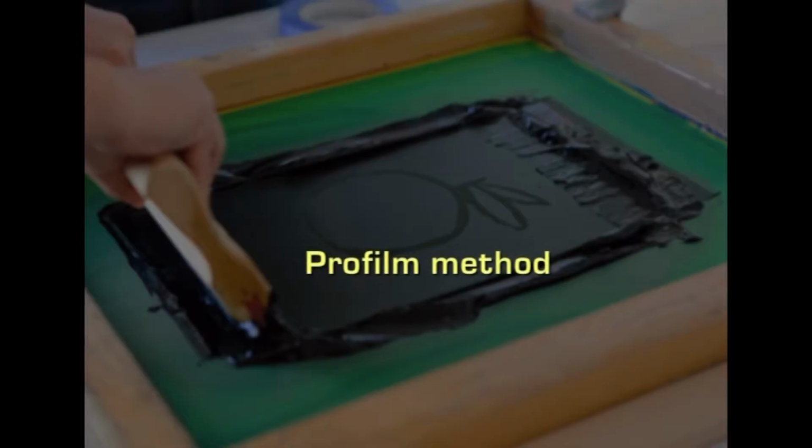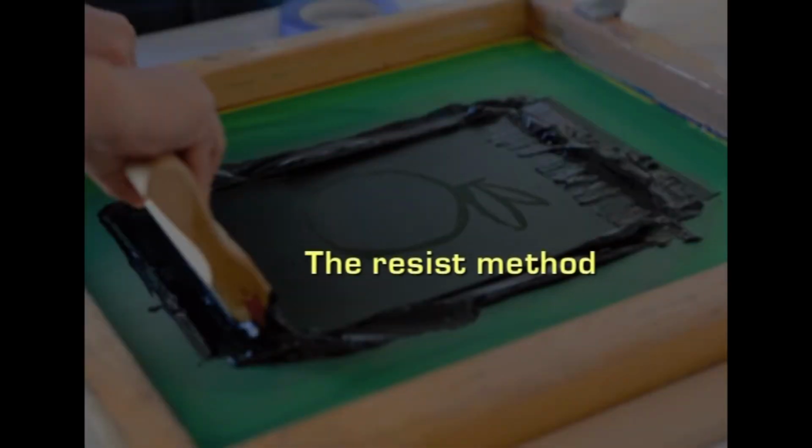Coming to the second method, the Profilm method. In this method, a profilm is placed over the design and the required motifs are cut out with a sharp knife so as to form a stencil. This stencil is placed on the silk screen and is ironed so that the profilm gets fixed onto the screen and is ready for use.